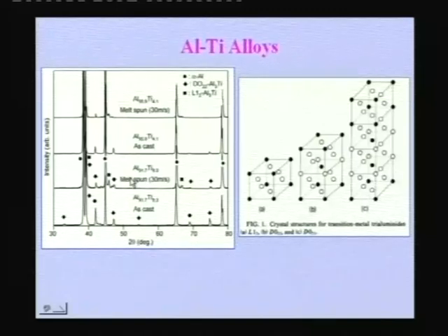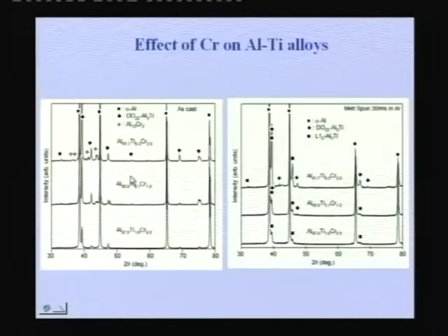Maybe if you go to much higher cooling rates, one can probably suppress this. Or if you add certain alloying elements, possibly it is easier. So people try various alloying elements. One such element is chromium here.